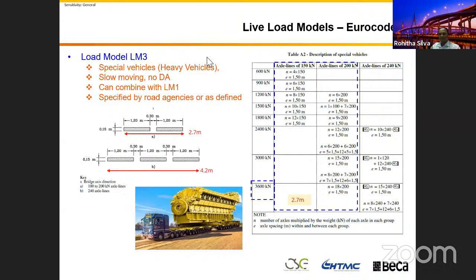If I just give an example, these are not exact numbers, just my reading and understanding: the fatigue effect of a truck versus a car is more than 1,000 times. So if you put more, heavier trucks in there, that will amplify it more. Then, especially if it is a steel bridge, the design life of the bridge will reduce significantly.